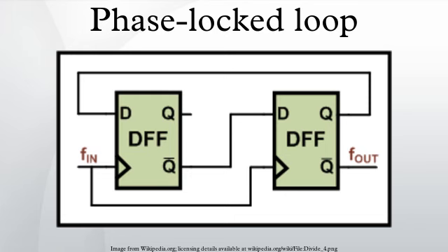Clock distribution: typically, the reference clock enters the chip and drives a phase lock loop, which then drives the system's clock distribution. The clock distribution is usually balanced so that the clock arrives at every endpoint simultaneously. One of those endpoints is the PLL's feedback input. The function of the PLL is to compare the distributed clock to the incoming reference clock, and vary the phase and frequency of its output until the reference and feedback clocks are phase and frequency matched.